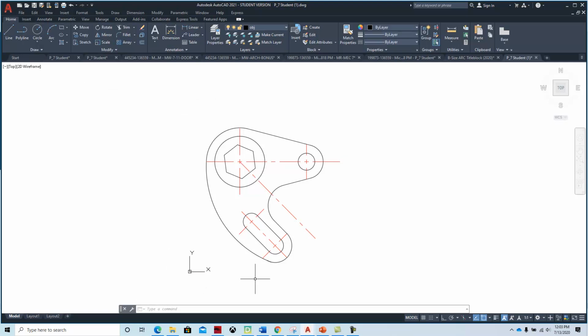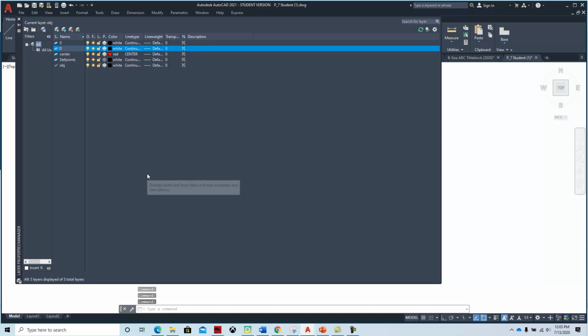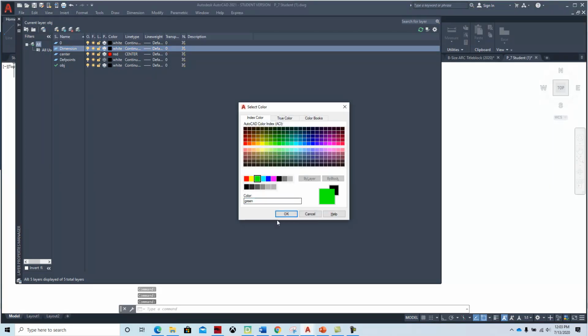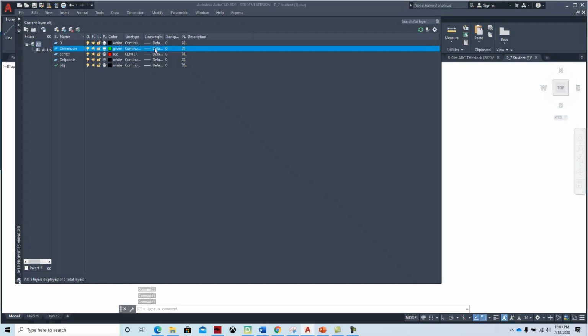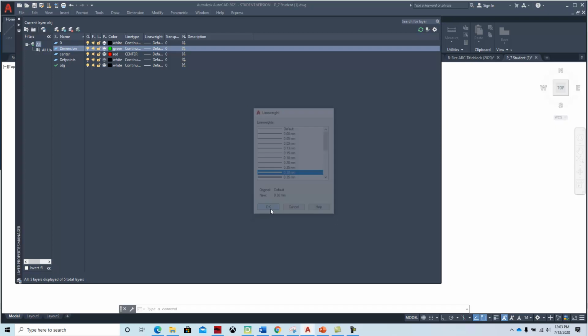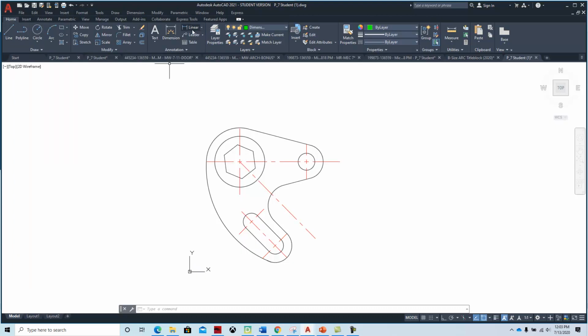So if we come back here and create a layer for that, line type would be continuous, line weight 0.3 millimeters, and then we'll make it current, and then we can close this. To put a linear dimension on, we can go from this endpoint here to this endpoint here, and then place that dimension.